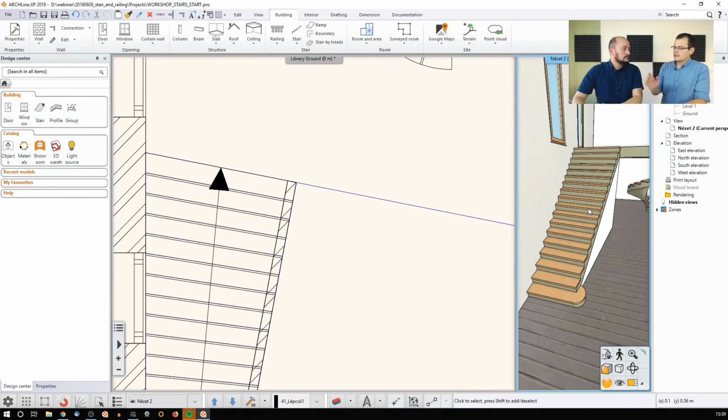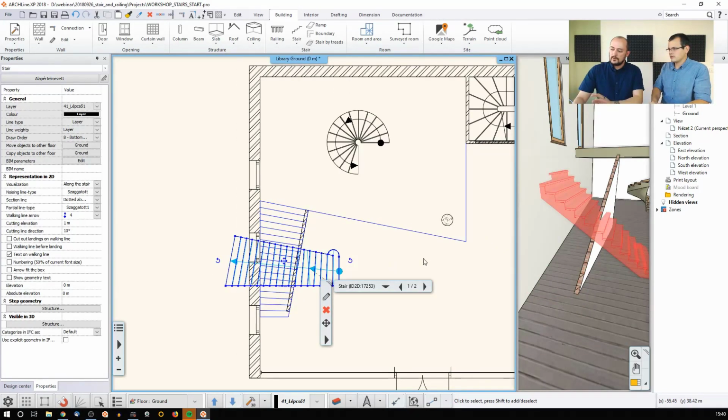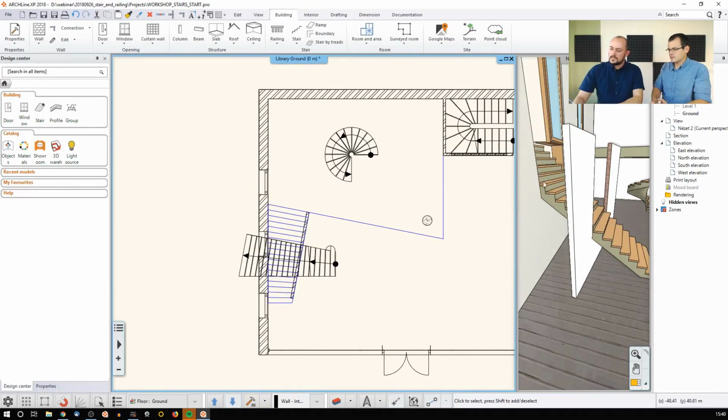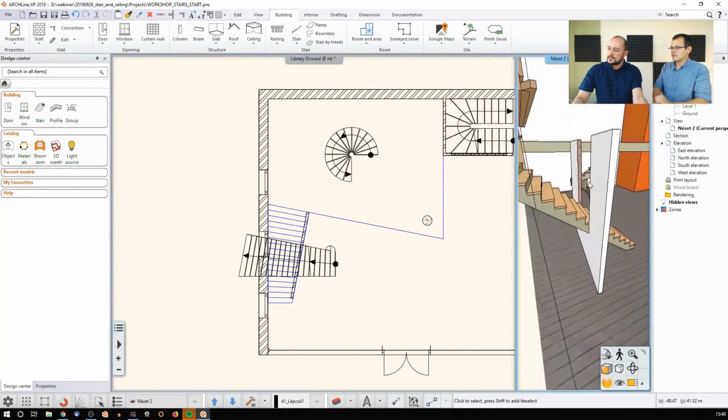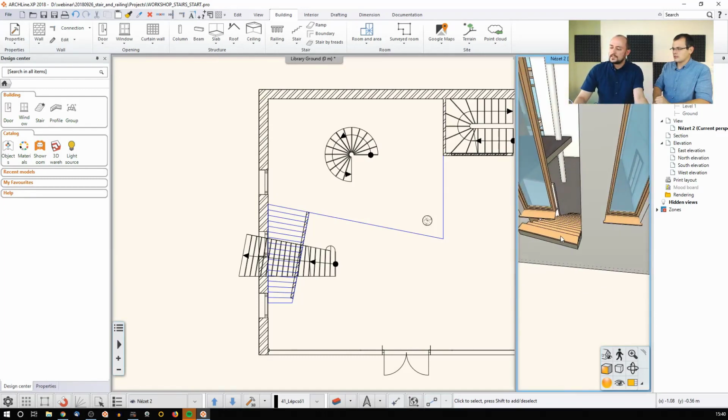The wall. What happens if, let's just try just for fun, what happens if the staircase goes through the wall? For instance, from inside it goes all the way to the outside. Maybe it's a fire exit. Okay, so just for fun, let me rotate this, and this works anywhere. If I rebuild the 3D, now you will see a different result. See, this is how it goes. It literally cuts through all the walls wherever it goes through. So all you need to do is to make sure that the staircase is set properly. So you just need to enable cutting of the walls.